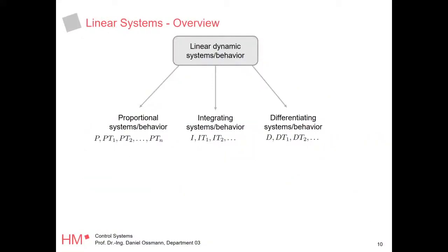And why we talk about systems and behaviors and use them the same way, I'll talk about that in a second. But let me get with this first. We talk about proportional systems, we talk about integrating systems and differentiating systems. And here it's really important for you: the systems, at the end of the day, are ODEs. They are a mathematical description of your hardware. If the system is acting proportional, integrating, differentiating, or any combination of those, it's really what it means.